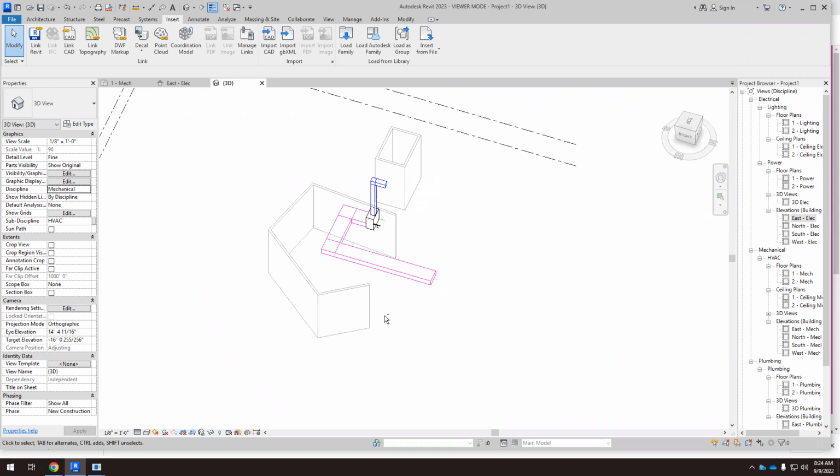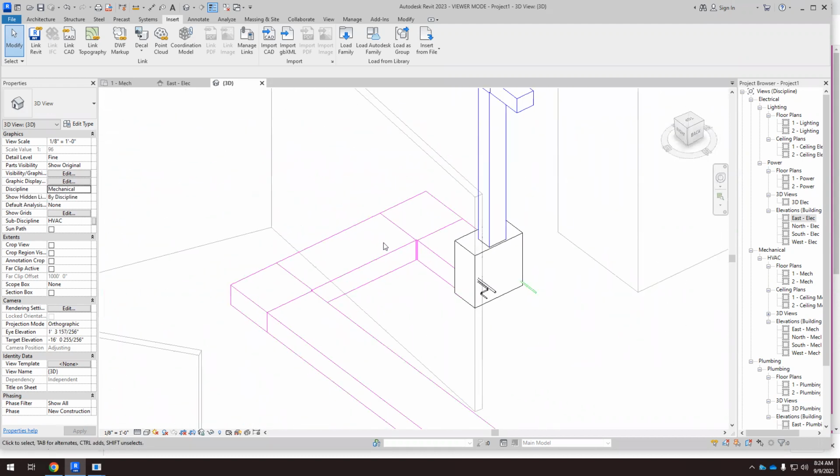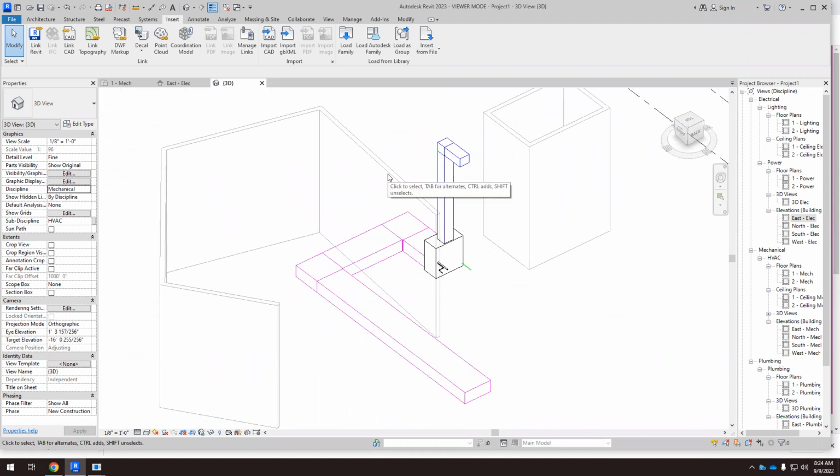And if something like this happens, what's this? Okay, so we have a duct that goes through this wall. So you have to do something for this wall. If there's a roof here and we have a vertical duct that goes all the way up, we have to open a hole on the roof or whatever. And that affects the design, because if we open a hole in the roof, what about the waterproofing? What about the thermal insulation? What about all these things? So we have to rethink the project again.